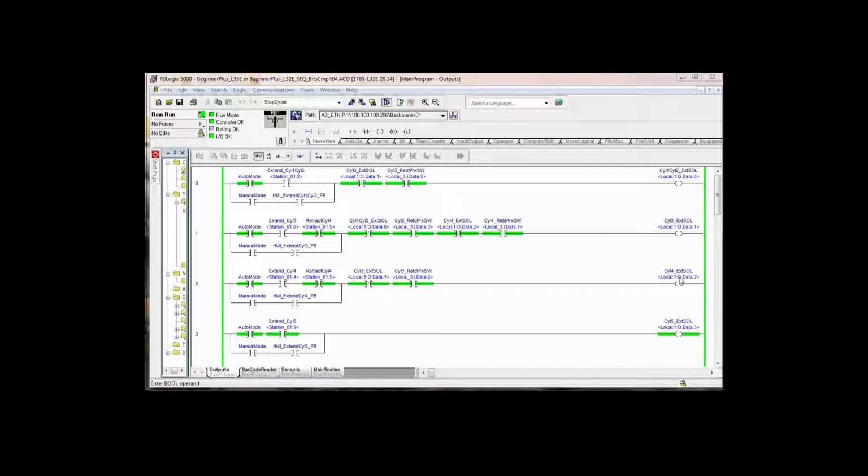First of all, you can look at the LED on the controller I/O module to see if this bit is turned on. In other words, there's an LED that will light up. Now, if this was a 1400 or 1000 or RSLogix, some of them have LEDs, some of them have an LCD display, and you can put it into I/O display and you can look to see if it's getting turned on. Now, just because the controller says it turned it on doesn't mean you've got voltage actually going out there to the solenoid.